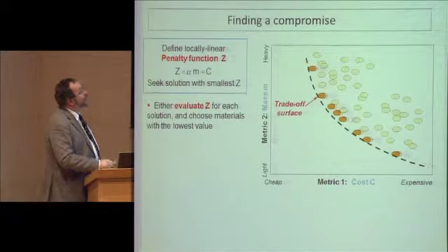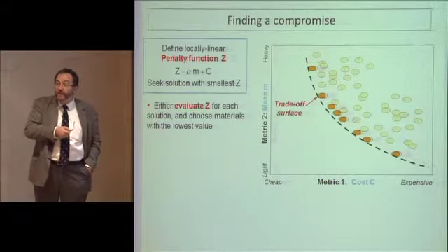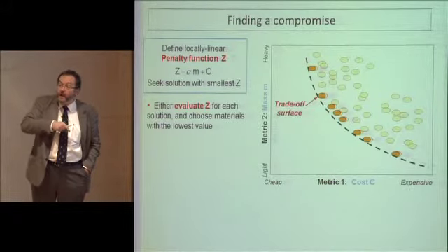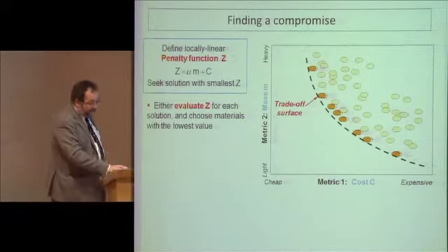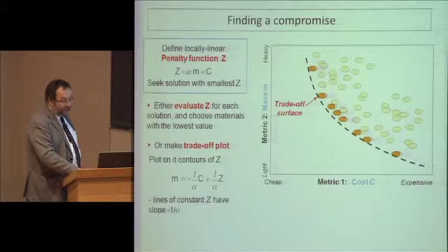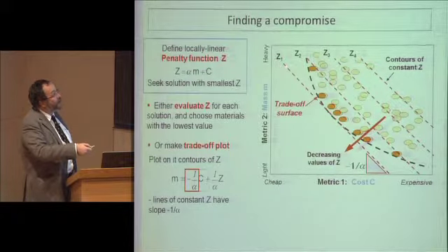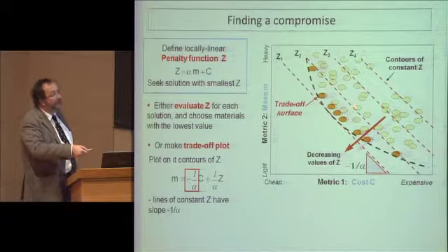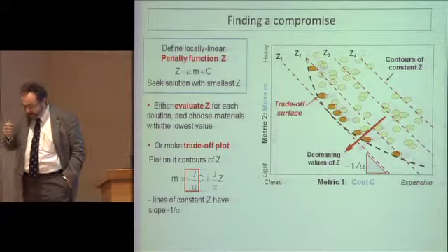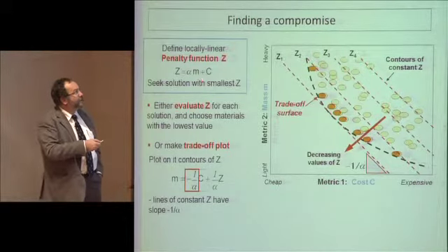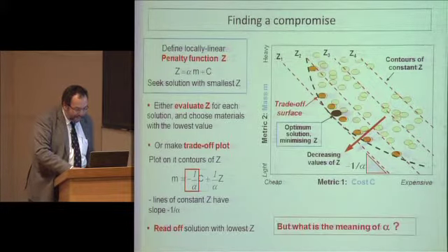So if you want to go deeper, you say, I have a trade-off factor, which is how much am I prepared to pay to reduce mass. So you have a combination of mass and cost and a trade-off factor, which says I'm prepared to pay such or such amount of money to save 1 kilogram. So in addition to your Pareto curve here, you have a tangent between equiperformance and the front that's going to tell you what the optimal solution is. It sounds very simple, but how do you actually build these trade-off factors? And that's a big problem, because first of all, people don't really want to tell you.